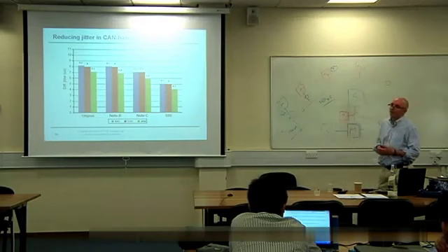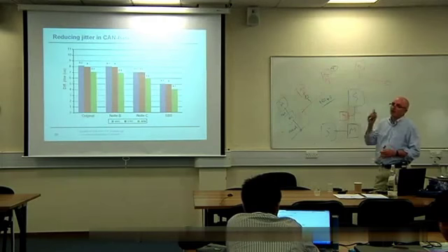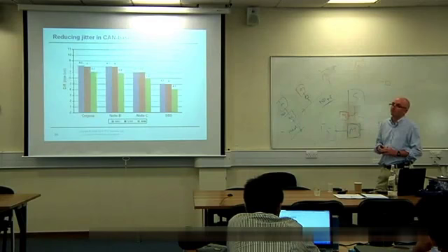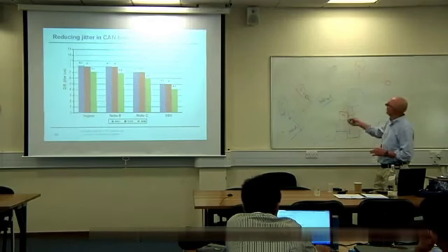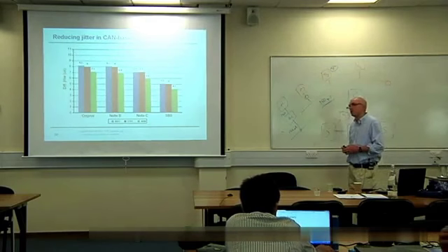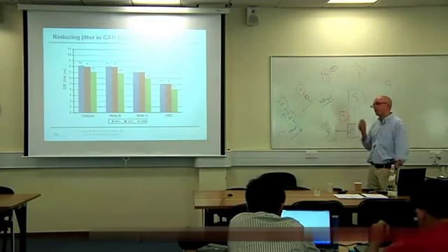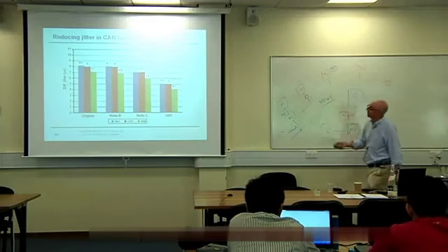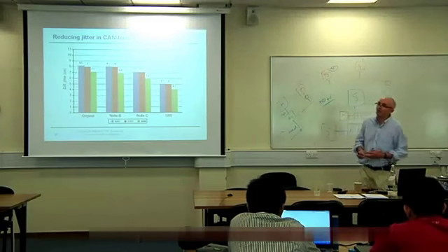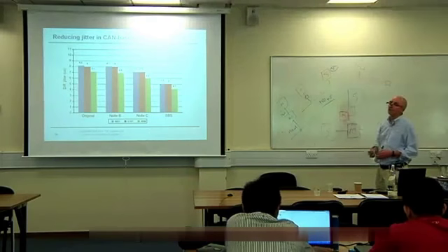Change the protocol a bit. Have the master node just send empty messages. Allow all of the nodes on the bus to see all of the messages on the bus. So there are different ways of doing the communications. If you want zero jitter, the master needs to send out the same message every time. So you can't have the master sending out different data contents.